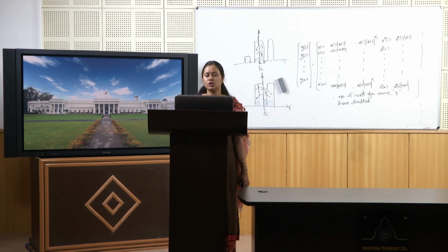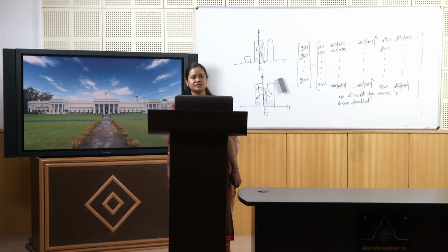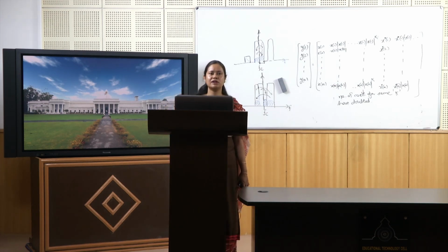If we filter any of this out, it will not make a perfect model, because we are missing that distortion data. So, this requirement is stringent, especially when we are going towards 5G, where they talk about a 200 megahertz or 400 megahertz bandwidth signal. Then it will be very difficult, because we will be dealing with a 1 gigahertz sampling rate of the DAC and ADC. So, this is one limitation, and it is coming from the digital circuits, but the advantages are there also,